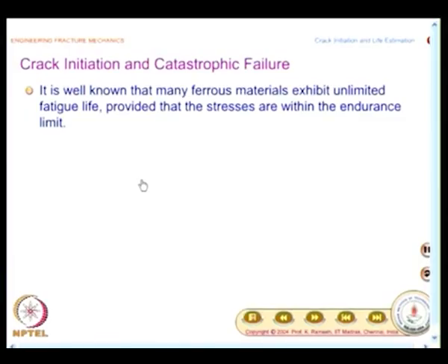There is a crack initiation phase, and here we also bring in our understanding of fatigue. In the case of fatigue, you have a concept of endurance limit. So, that shows that for cracks which are very small and loading which is quite small, under such conditions the crack may not grow in service. This is the conclusion that we can arrive at. So, that means there has to be a threshold stress intensity factor below which cracks may not initiate. So, this concept was advanced.